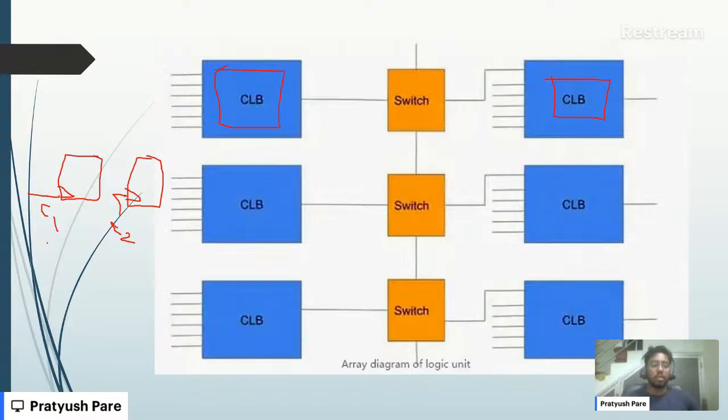These clocks have some phase differences and frequency differences also. Then if you want to transfer some data to this flop, there is a chance that you may miss the data, right? So that's where we put the synchronizers. Synchronizers are used to go from one clock domain to another.